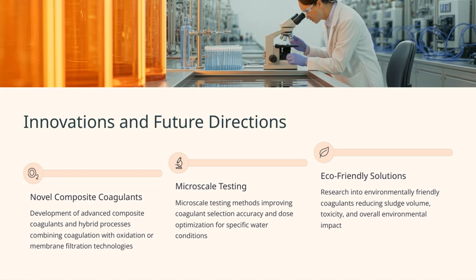Next, microscale testing is gaining importance. These miniaturized testing methods help us select the most effective coagulants and determine optimal dosages more accurately, especially tailored to specific water conditions. This means better performance with less waste and cost. Finally, there's a strong push toward eco-friendly solutions. Researchers are developing environmentally friendly coagulants that aim to reduce sludge volume, lower toxicity, and diminish the overall environmental footprint of water treatment processes. All of these innovations are aligned with our broader goal, making water treatment more efficient, sustainable, and adaptable to future challenges.